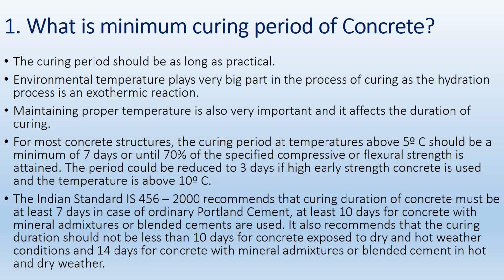The first question is, what is the minimum curing period of concrete? The curing period should be as long as practical. Environmental temperature plays a very big part in the process of curing, as the hydration process is an exothermic reaction. Maintaining proper temperature is also very important, and it affects the duration of curing.